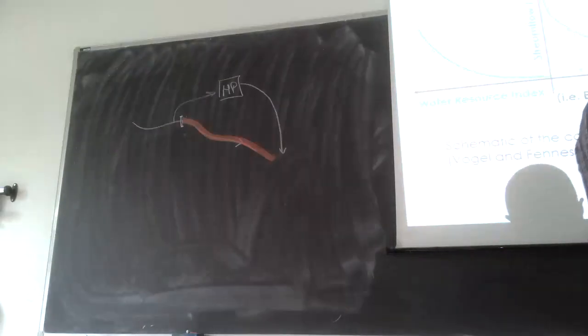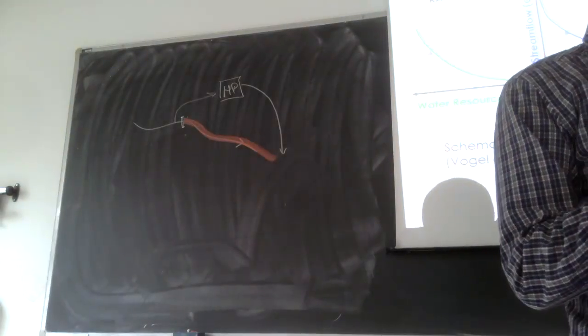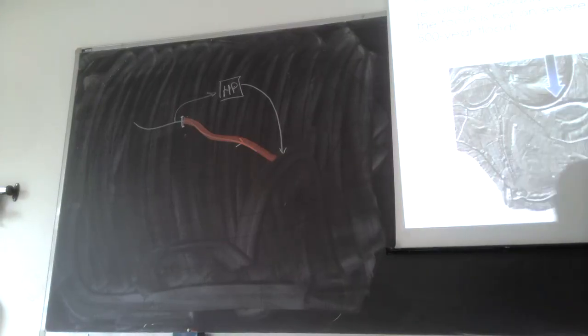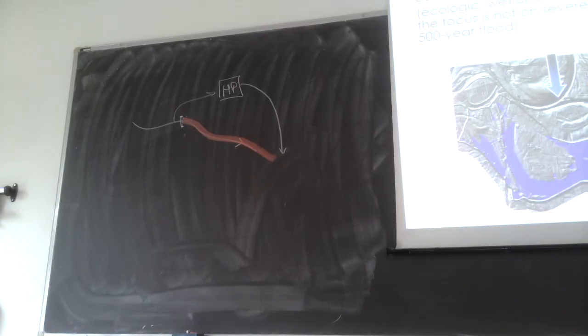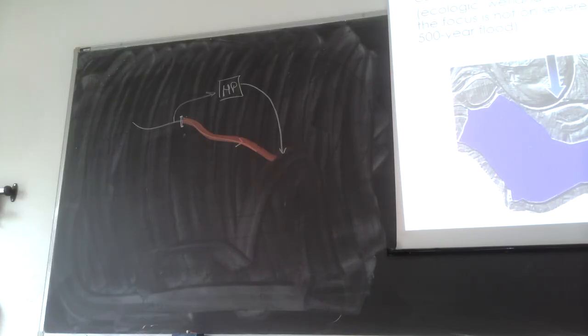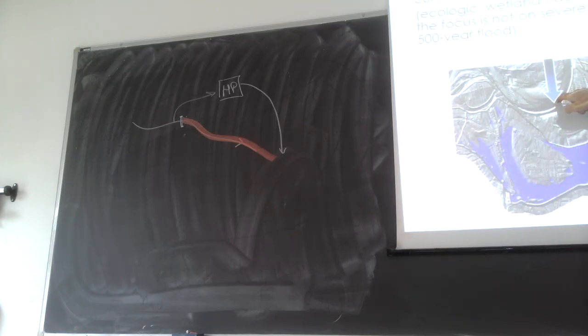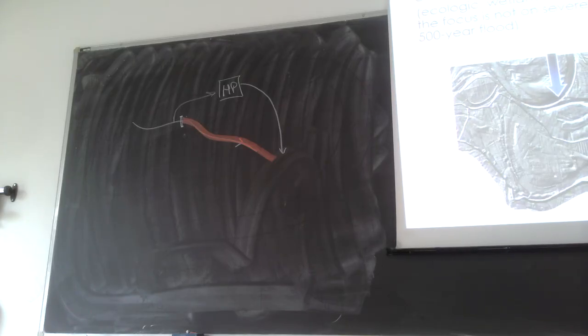Okay? Let's suppose you have a one-to-one relationship between the river stage, so the water level in a given river cross-section, let's say here, okay? You have a one-to-one relationship between the river stage and the stream flow. This is what we called 3 weeks ago a rating curve in the strict sense. Water level or water depth, stream flow, right? Stream flow increases, water level increases in the river cross-section. Make sense?